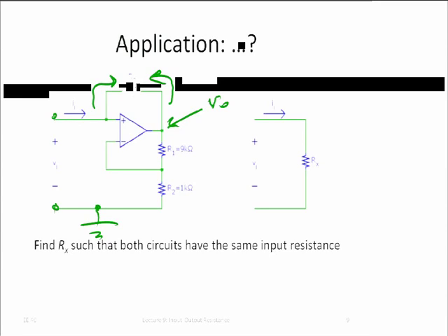In practice, of course, a real op amp is not going to supply 1,000,000 amps, but then mostly we wouldn't want to, right? I mean, we make RF a few k ohm, and then the current that's going to flow is a few milliamps, right? And so even practical op amps, most of them, happily supply a few milliamps. So it really doesn't matter what the value of RF is. And so now if I want to analyze my circuit, figure out what is V out, I can just analyze it for the case where RF is infinite and then RF isn't present, and that's why I erased it.